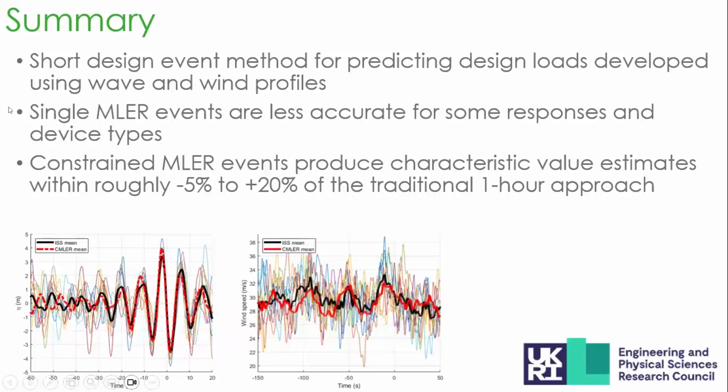As a summary, we've come up with this short design event method for predicting design loads. The single short design event, like the single focus wave, is less accurate for some responses, so it needs to be used with caution if thinking about mooring loads, particularly for semi-subs and barges. And then overall, for the constrained cases, we had results within roughly -5% to +20% of the traditional method.